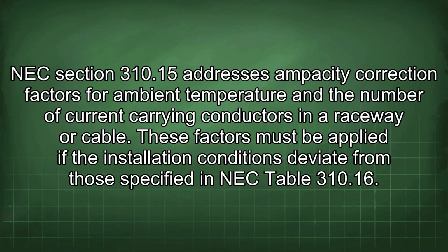NEC Section 310.15 addresses ampacity correction factors for ambient temperature and the number of current carrying conductors in a raceway or cable. These factors must be applied if the installation conditions deviate from those specified in NEC Table 310.16.